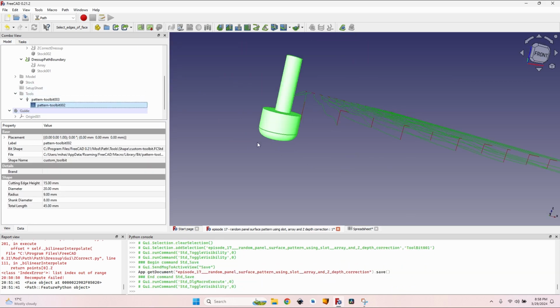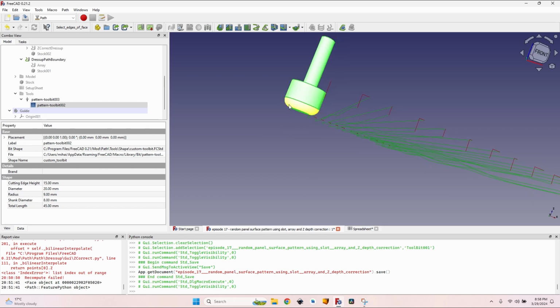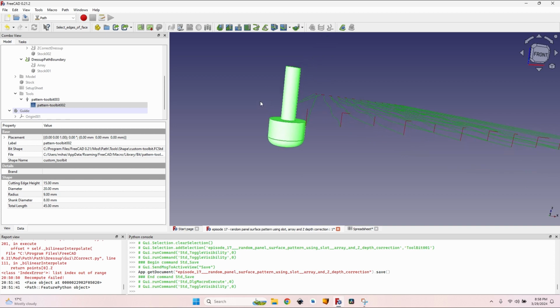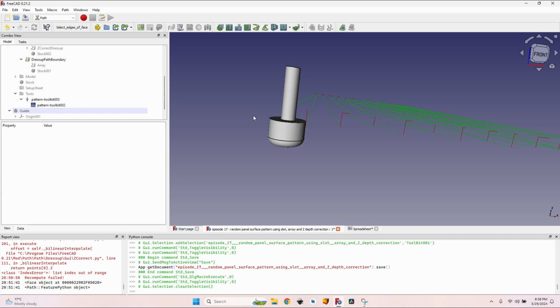I've used a bowl bit. By varying the depth of the cut, it will create a wider or a narrower channel. I can increase the radius, I can modify all these dimensions, I can go to the workshop and find a real bit. For example, I can use a V-bit to create patterns, but this is the part where you have to be creative, you have to test it out and create your own patterns using this file.